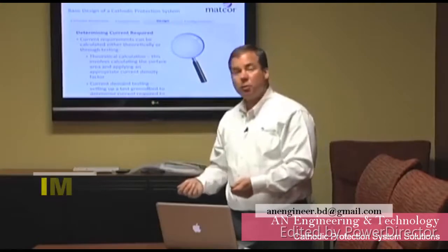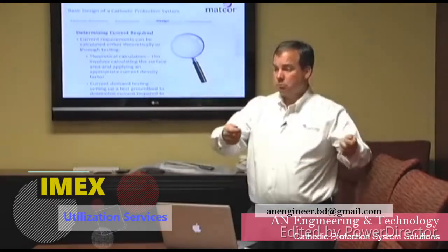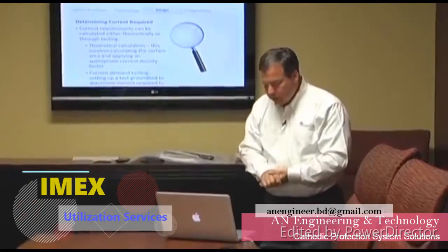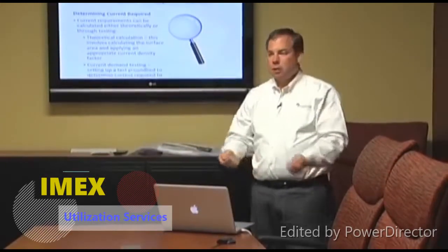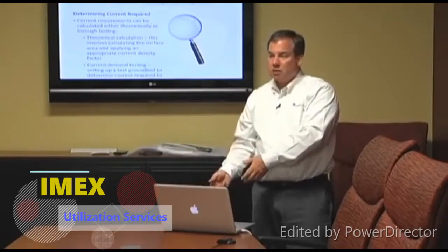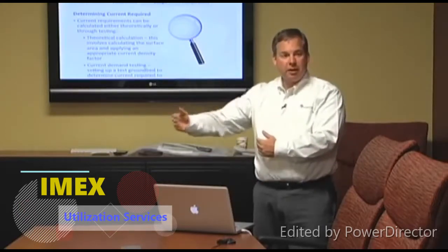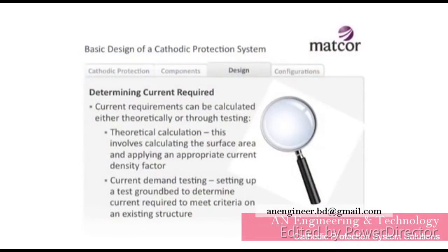Another way to do it is to go out in the field and test it. Okay, I take a portable power supply. I drive an anode into the ground or a stake into the ground. I run current off of it. I measure how much shift I get to the structure. We call that a current demand test.